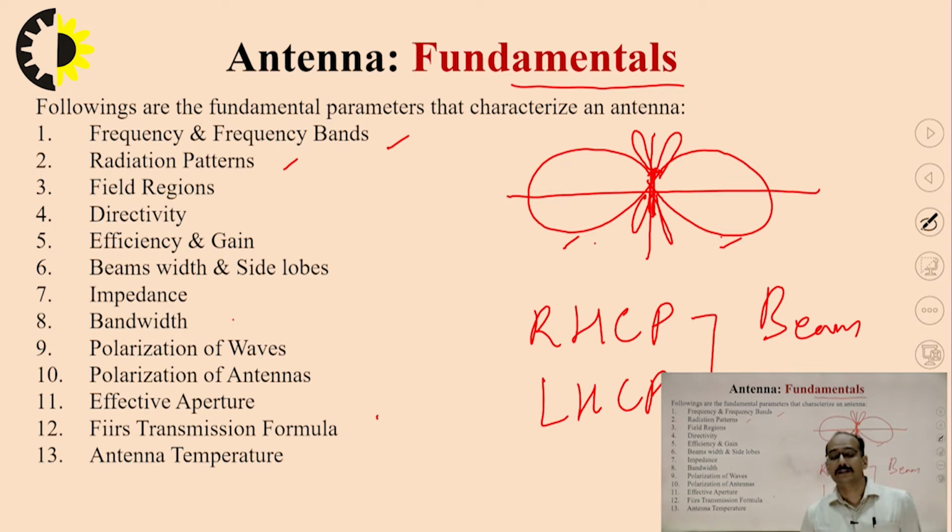When your satellite is used for transmission and receiving, sometimes the satellite antenna has to transmit data over a large region, then it will use a wide beam antenna. But when you want to cover a specific area, then you require a spot beam, and that spot beam requires specific information about the polarization. That's why the polarization parameter is also very important during the selection of the antenna in a satellite system.